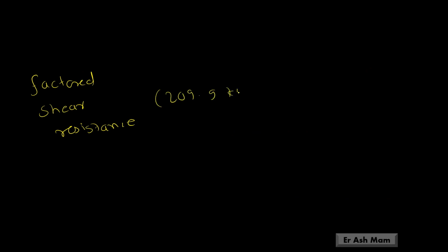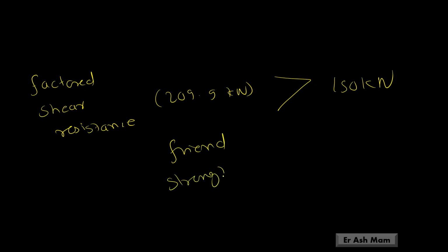It means factored shear resistance is 209.9 kilonewton, which is greater than 150 kilonewton. It means our strength is greater than our enemy. Therefore, safe.